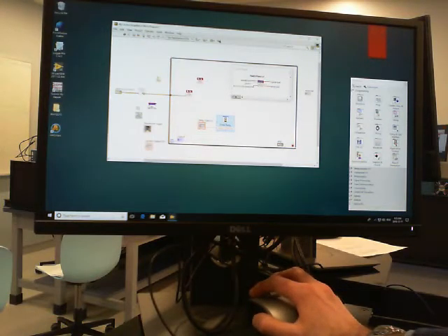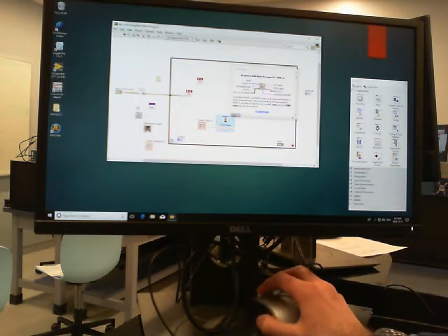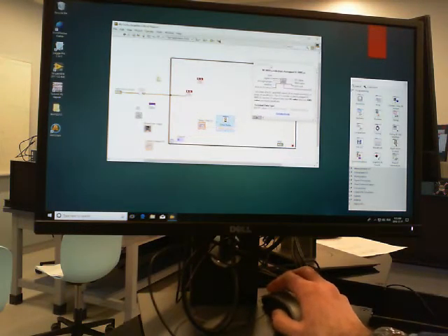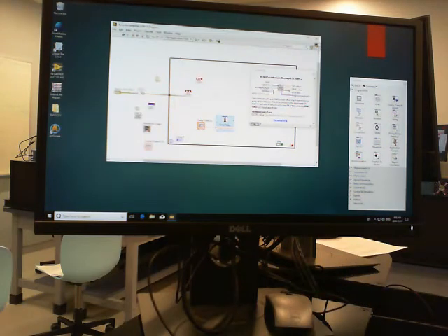And the different VIs that you hover over take different things. This is the phase shifting sub VI that you're going to be using to build your lock-in. This is the sub VI that's going to do the averaging for you. A lot of these inputs don't actually have to get wired up, just the signal in, and you'll just be looking at either the RMS or DC value on the output, whatever is relevant. And away you go. So you'll have a reasonable amount of time here to set up this program.